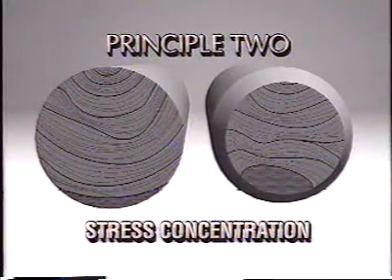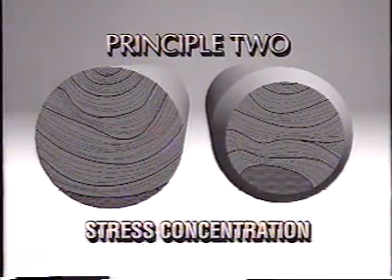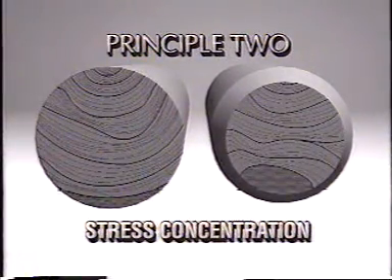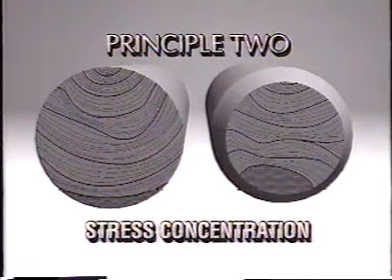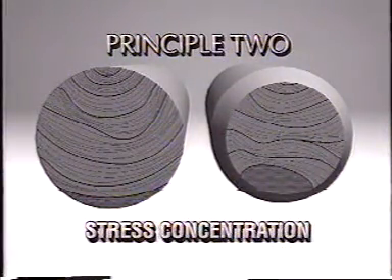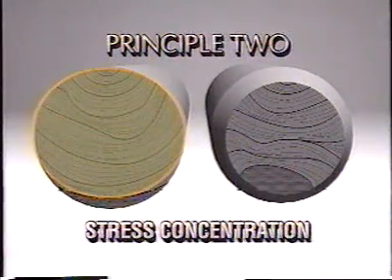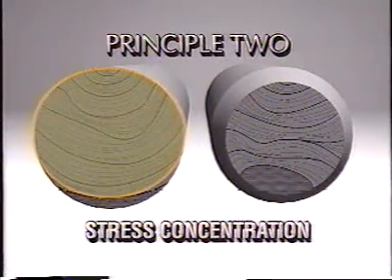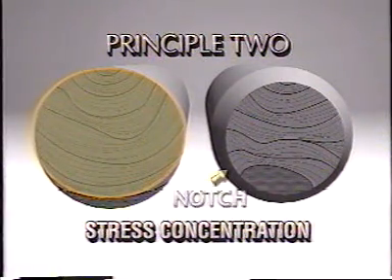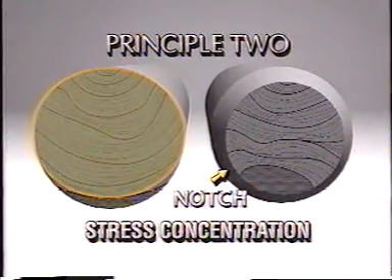Principle number two. When no stress concentrations occur at the surface, cracks will propagate more rapidly near the center of a section. Propagation occurs because deformation constraints cause the stresses away from the surface to be triaxial and more severe. However, when a stress concentrating notch is at the surface, the stress near this notch may be more severe than when farther below the surface. Under conditions of severe notching, irregularly shaped crack fronts will sometimes be observed.